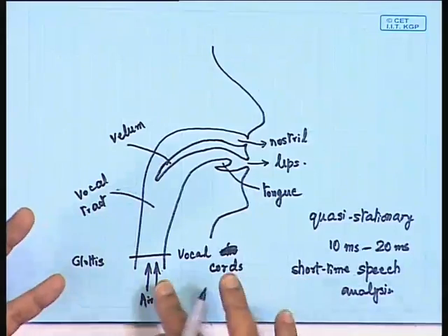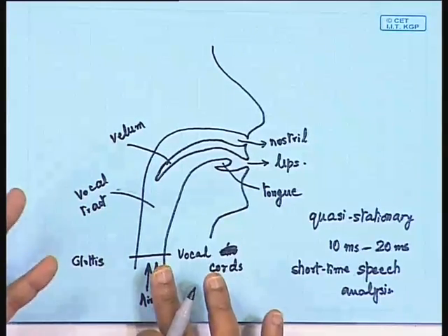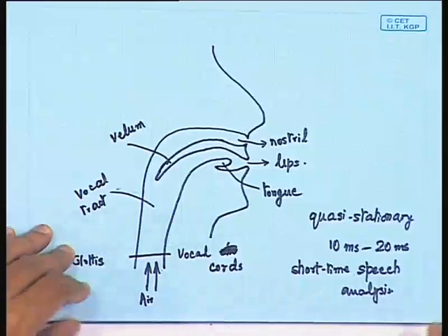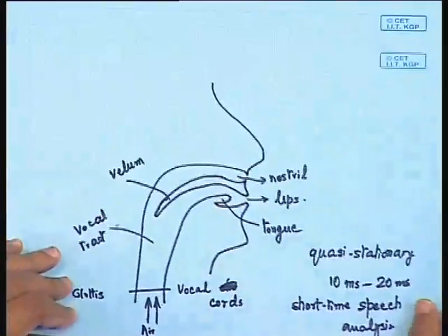In fact, using our articulatory organs like the velum and the tongue, we are able to alter the shape of the vocal tract dynamically, so that it is not a kind of filter that has a constant behavior with respect to time. It keeps changing. So it is a source of excitation that we can imagine at the glottal passage, followed by a time varying filter.